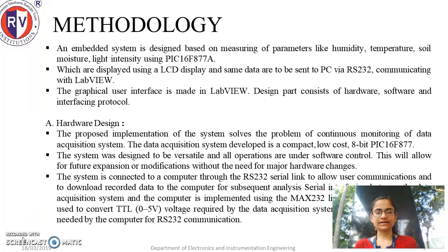The system is connected to the computer through an RS-232 serial link to allow user communication and to download the recorded data to the computer for subsequent analysis. The serial interface between the data acquisition system and the computer is implemented using a MAX232 line driver/receiver, which is used to convert the TTL voltage required by the data acquisition system to the -12 volt to +12 volt needed by the